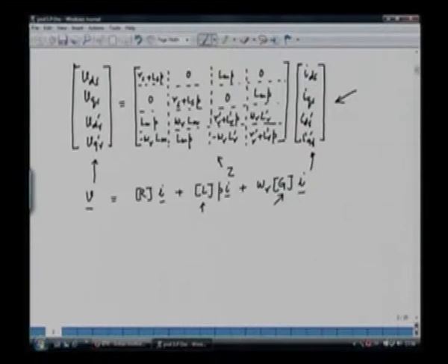So we can write down what is the G matrix here, because this G matrix is useful in calculating the torque of the machine. So from this 4 by 4 matrix we can see that this element is having omega r term, this element is also having omega r term, this is having omega term, and this is having omega term. So this G matrix will have 4 elements.